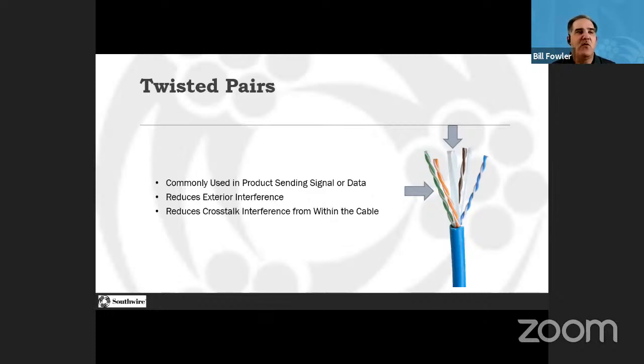And as we'll talk about category cables here in a little while, but as you go up in the category ratings, that twist per foot gets more, okay? So our higher rated cables will see more twist per foot. The other thing we saw is, you see, I've got another arrow with that center divider, is that as we got into the category 4, 5, and 6, it was very important to make sure those pairs laid the same way in the cable. So that separator in the center is really a guide to keep those pairs in the same place and the same distance from each other, so we don't get any crosstalk inside the cable.